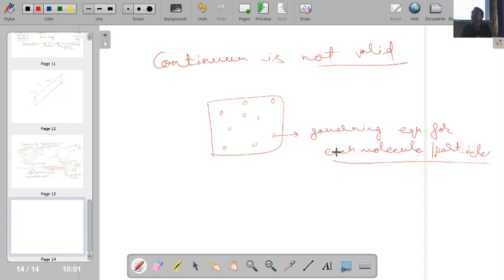If we solve the behavior of each molecule and then do some statistical averaging, as we do in statistical thermodynamics or statistical mechanics, then we will be able to predict the behavior of the overall system. So from a fundamental perspective, this is the most fundamental. Here you analyze the motion of each and every molecule present in the flow field. However, at the continuum level, there can be a variety of molecular activities; we just consider the averaged properties and analyze the average flow situations. So this is the most fundamental, where molecules are to be considered.